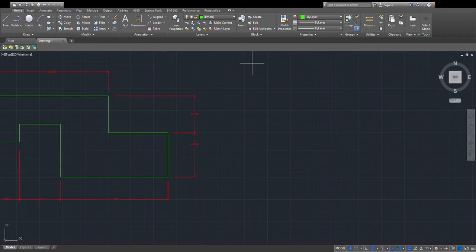I'm going to select another polyline. Now, for this one, I'm not going to draw a square with corners, and the reason is we need to discuss one type of dimension lines. Okay, so I'm going to draw a triangle. Again, escape gets you out of the drawing tool. Now let's go back to the layer properties and make our dimensions current.